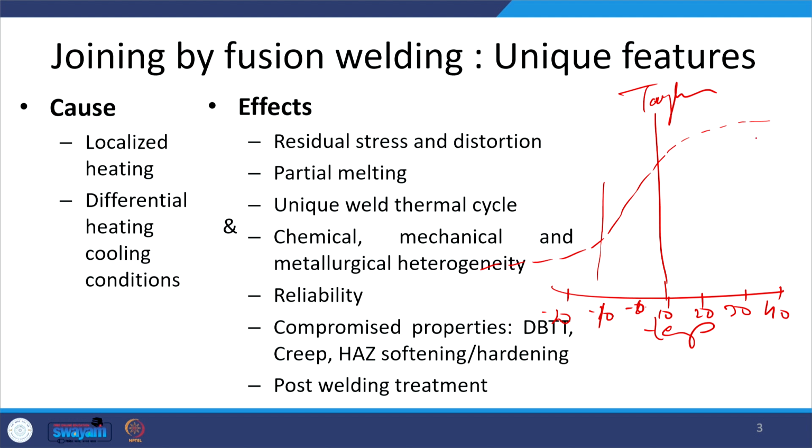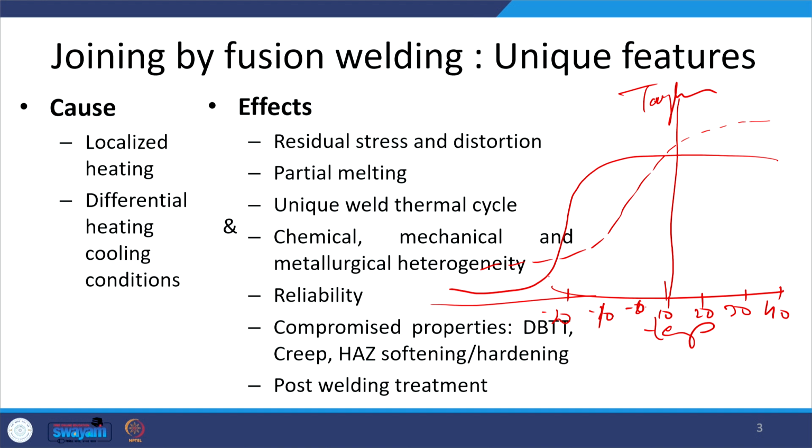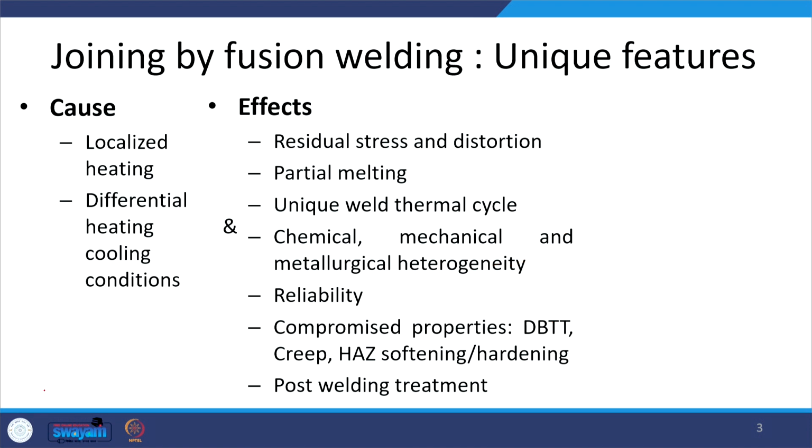But there is another possibility that this drop can take place at much lower temperatures, where the metal continues to hold its toughness even at a lower temperature, and then the drop occurs at minus 30, minus 40 degrees centigrade. This may be true for the same simple base metal, but when the weld joint is developed, this drop starts occurring at a higher temperature, and that is why we say that the weld joints of certain metals increase the ductile to brittle transition temperature.